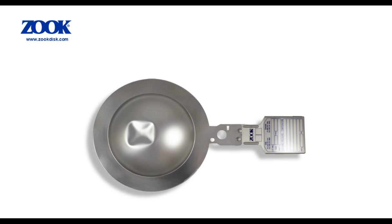Disc damage in the field is the single largest cause of nuisance bursts. I use the term nuisance burst loosely, and what I mean is a burst at a lower level than specified or expected. Nuisance bursts are expensive and result in significant loss of product or time or both, so they need to be avoided.